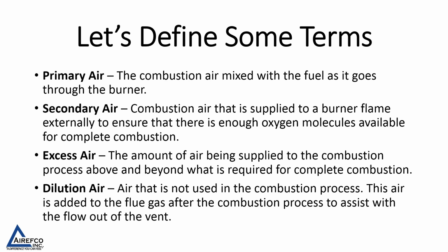Let's define some terms that are used in combustion analysis. Primary air is the combustion air mixed with the fuel as it goes through the burner. Secondary air is combustion air that is supplied to a burner flame externally to ensure that there is enough oxygen molecules available for complete combustion. Excess air is the amount of air being supplied to the combustion process above and beyond what is required for complete combustion. Dilution air is air that is not used in the combustion process. This air is added to the flue gas after the combustion process to assist with the flow out of the vent.